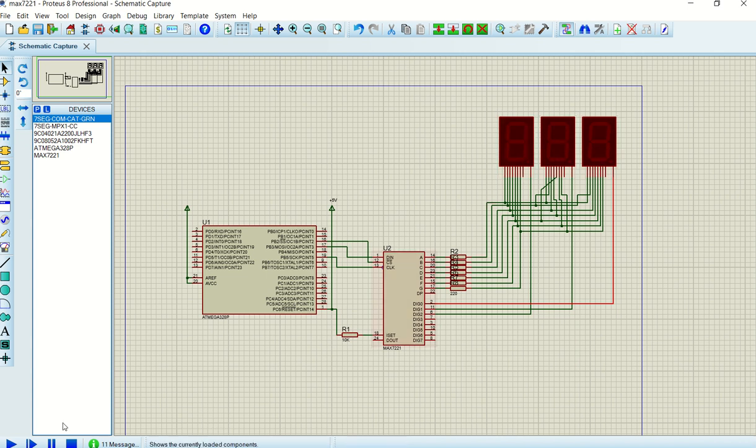So it will seem, if I can just get this to run in my program, I'm going to show you how we're going to display for U2. But as you can see there, it looks as if everything is on at the same time. Whereas if I can just hold this, as I've said, only one of them will actually be active at one specific moment. And as you can see, the output in this specific digit 2 is a 0. This is why the common cathode pin is actually pulled to 0. And this is why it will be displaying at that specific moment.